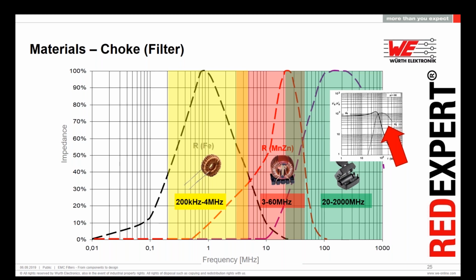when we talk about power inductors, we usually say that we should stay 1 decade before the resonant frequency, so we are not having so many losses on the core. And this is coming directly from this graph you have here. So basically, here are my losses. And when I'm talking about power inductors, we usually tell the customer to use the power inductors in this frequency range, so we are as far as possible from starting to have some losses. If we increase the losses, we reduce the efficiency of, for example, our DC-DC converter.